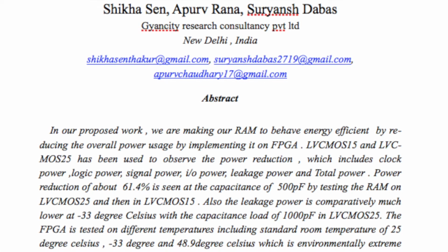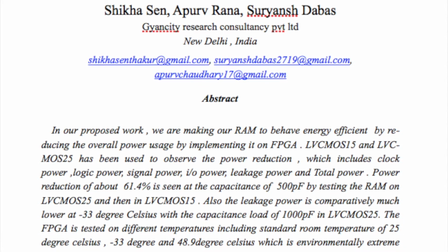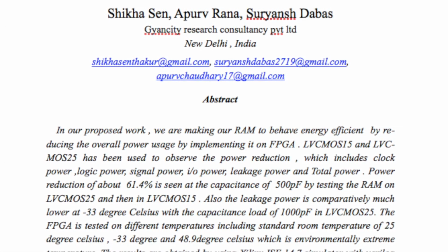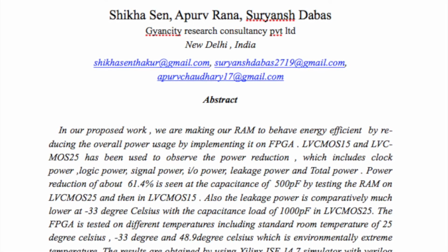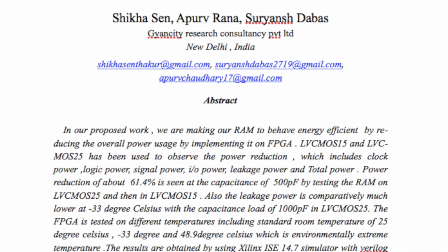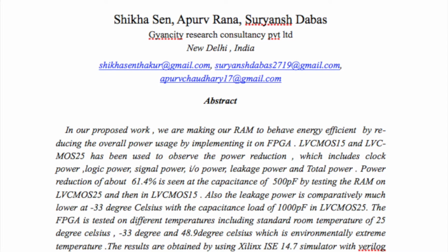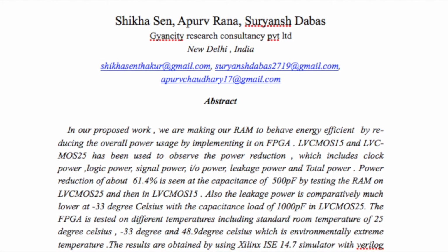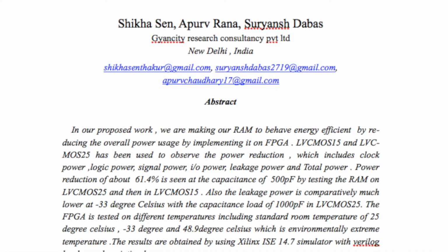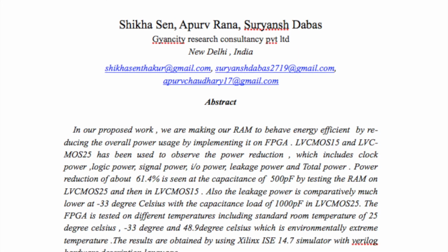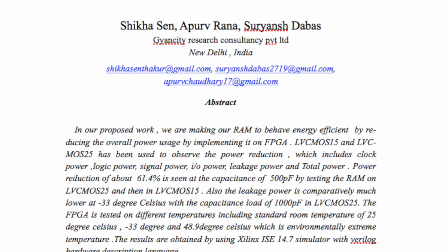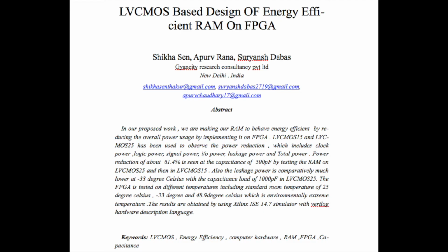We have used Xilinx ISE 14.7 version to test and obtain our results, and the hardware language that has been used is Verilog. We have implemented our RAM on FPGA using LVCMOS 15 and LVCMOS 25, that is at 1.5 volts and 2.5 volts. We are calculating total power consumption, that is the combination of logic power, signal power, input output power, and so on, so that we can try to minimize it at different temperatures and different parameters like change in capacitance, to get the value which can be used to make an energy efficient RAM.